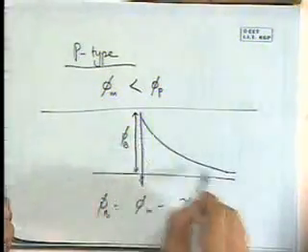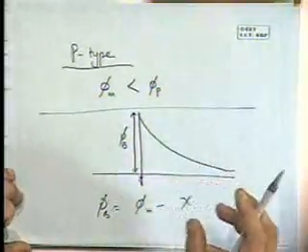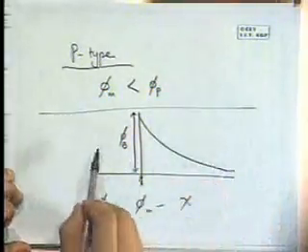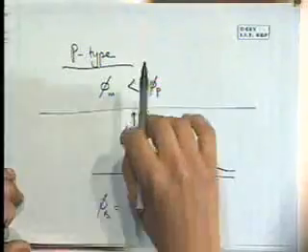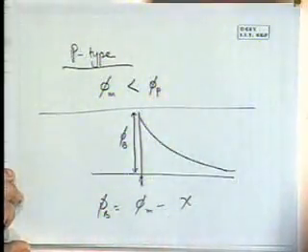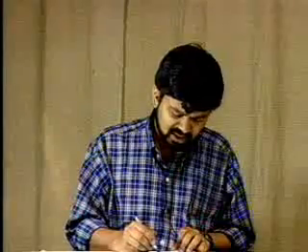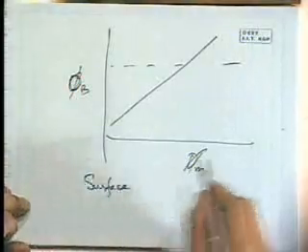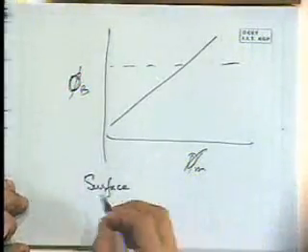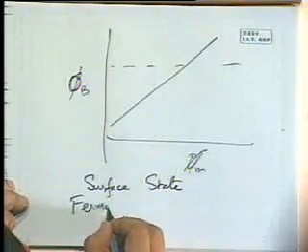And that's already bent, it's pinned. And the defect density is high enough that no matter which metal you put, it will not alter this band bending. Okay? That's known as the surface states, metal-induced gap states, called MIGS, or surface state theory, where we talk of the idea of Fermi level pinning.